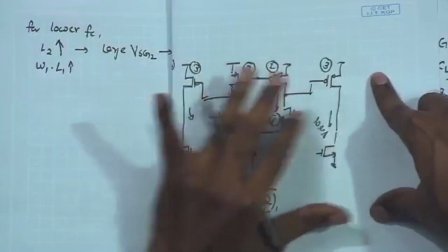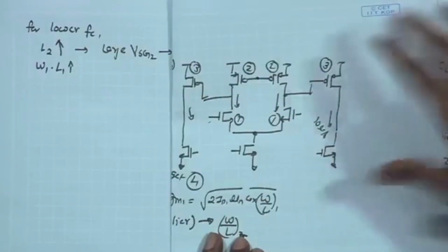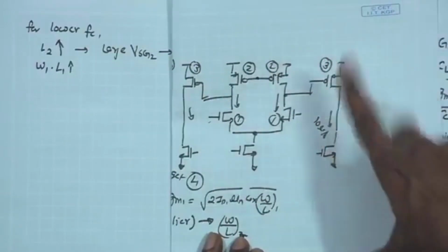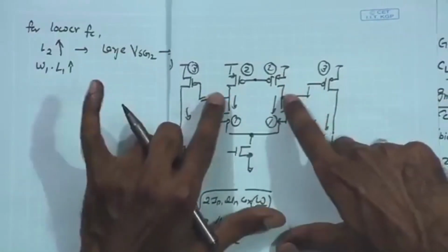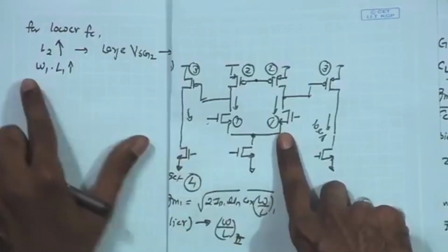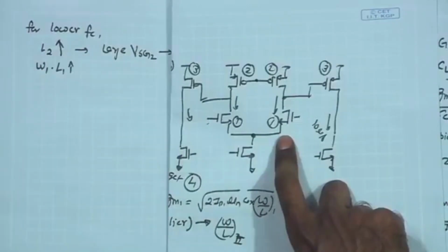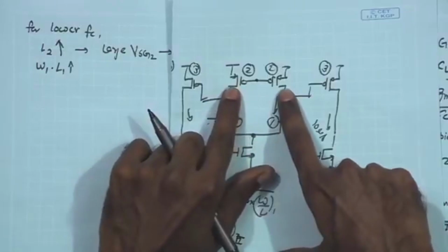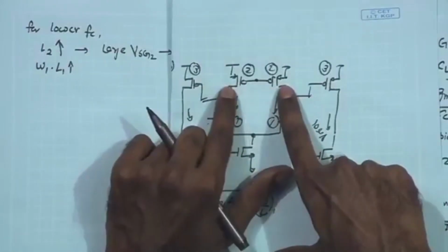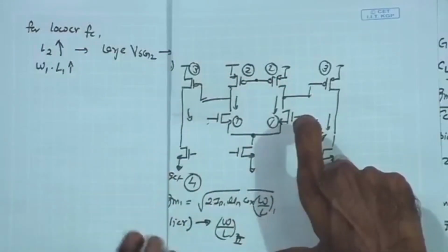But once again it is going to reduce the available signal swing, but that is not a significant constraint for the first stage, and therefore we can sacrifice the signal swing, we can ignore the requirement of the signal swing while focusing on noise minimization, while focusing on lowering of the 1/f corner frequency. So, let us just assume that this W and L1 is sufficient for giving us sufficiently low corner frequency, and then I try to maximize the channel length of the M2